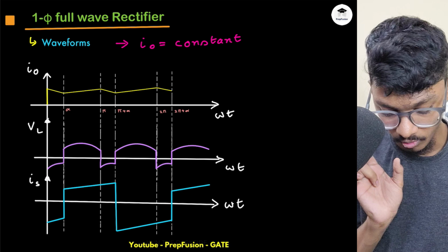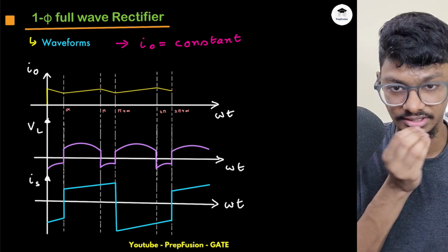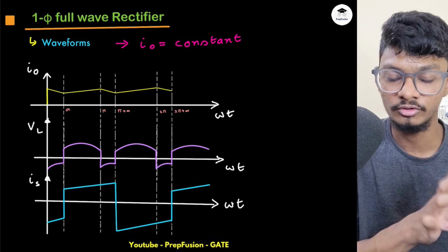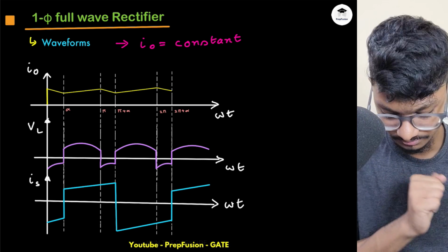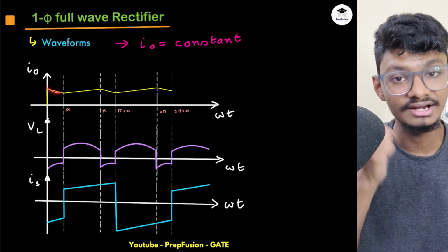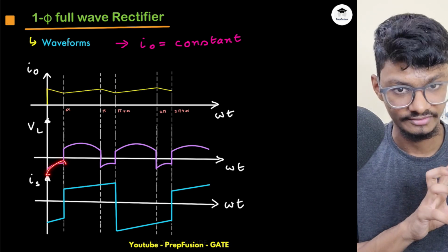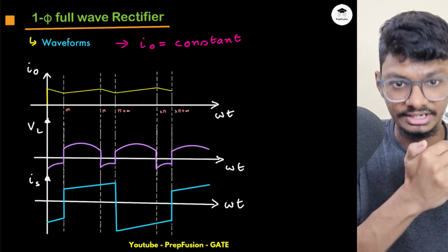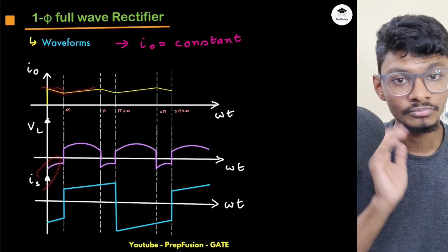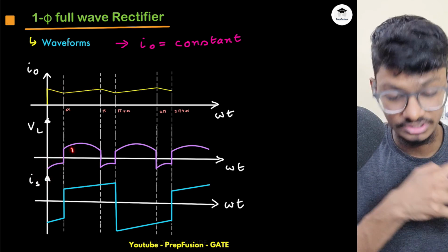If the current is almost constant, this will become linearized. We can linearize this. In the pulse response video I have also explained how we can linearize this. So what will the voltage be? Here, what is happening? Current is reducing. As current is reducing, obviously inductor voltage will be negative, because it is de-energizing and the slope is negative. Here current is increasing, that means inductor voltage will be positive because it is energizing.